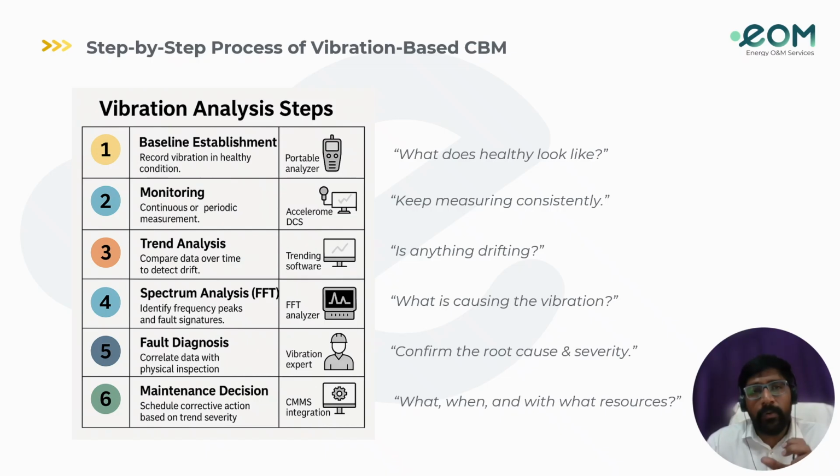It checks the mounting, like soft foot or any misalignment, which is done with laser alignment, and also considers the operational context, like load, cavitation, and process changes as well. And the next one, the main thing done in the last step, is the maintenance decision, meaning what should be done, when it should be done, with what resources, and with what process the maintenance should be done. Here all the decisions will be made.